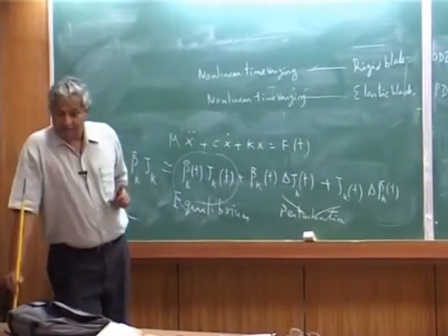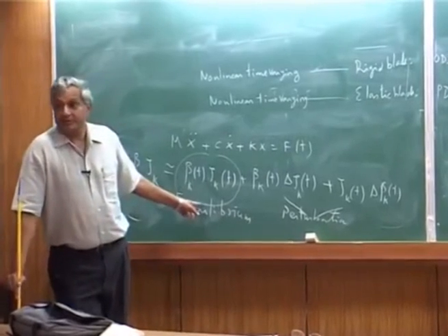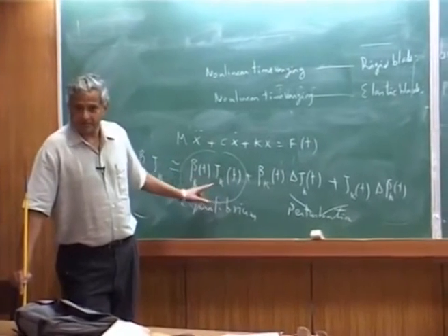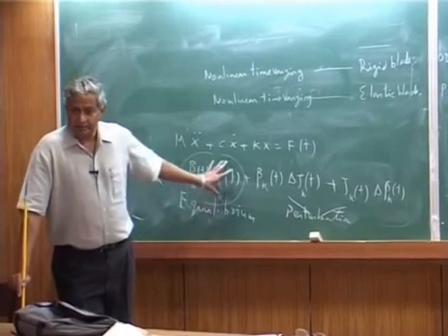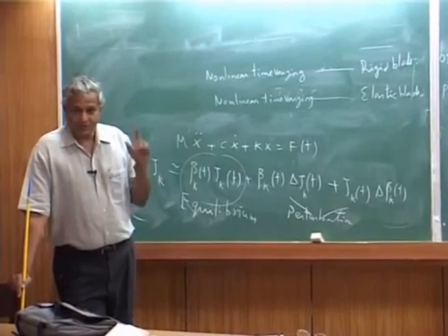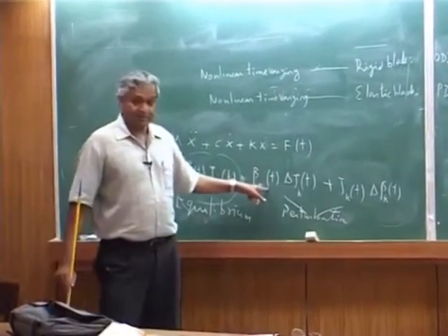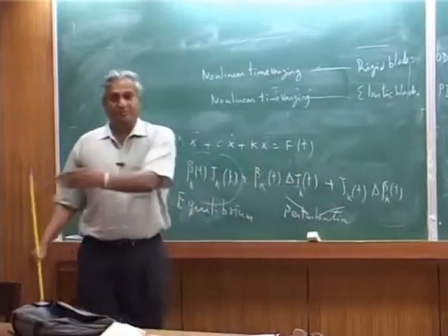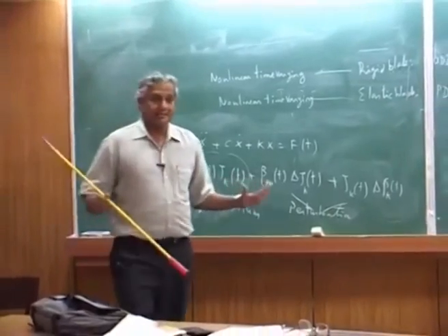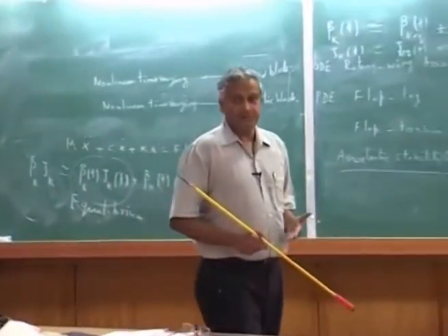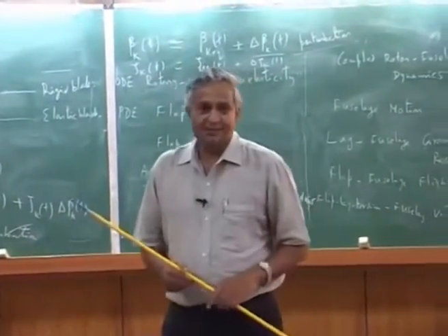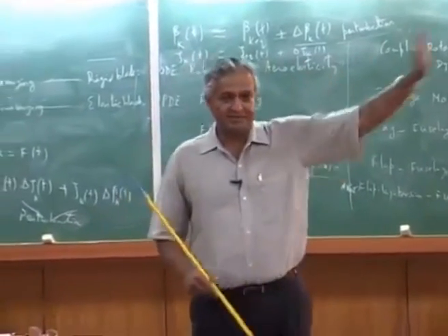You first solve the equilibrium equation to get beta and zeta. First solve this. This can be a differential equation, but you have to solve it. Once you solve that, you take that time varying solution and put it here. Then you solve the perturbation equation for stability. This is how helicopter problems are solved. Stability is analyzed in the perturbation, equilibrium is analyzed in the actual nonlinear system.